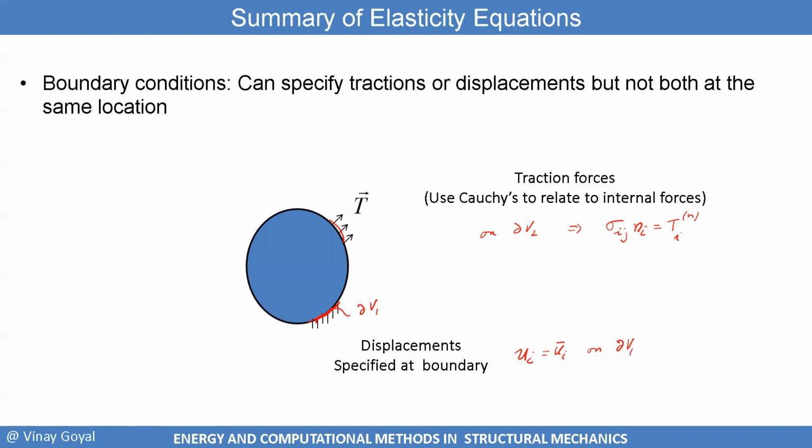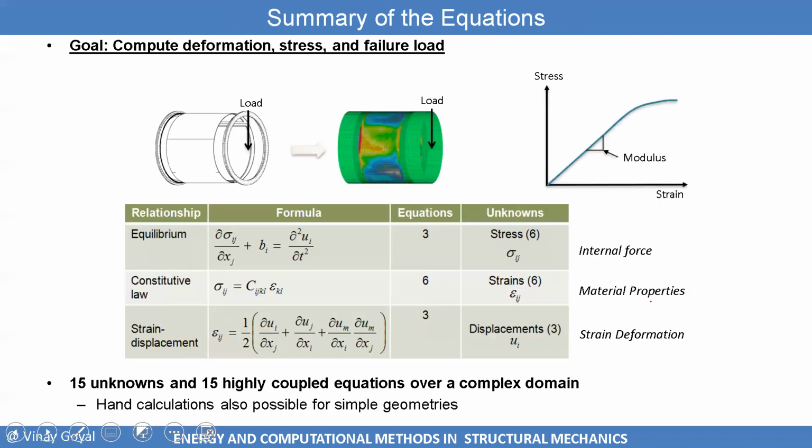That's what we discussed. From there, I want to remind you what the equilibrium equations look like in a different format. These are the 15 equations. Here I have 6, and you can see the Green-Lagrange strain tensor right here, which is symmetric because if you switch i and j, you get the same answer.